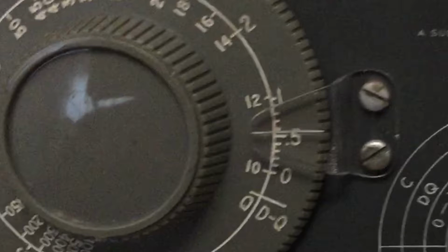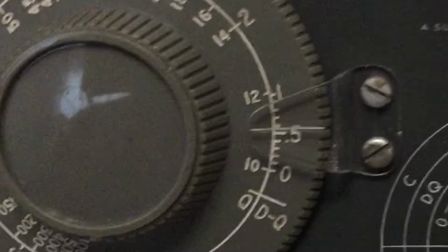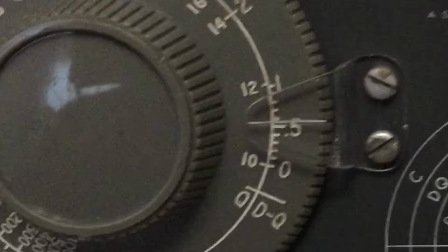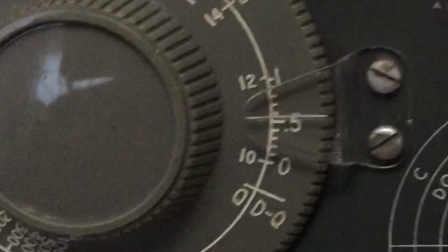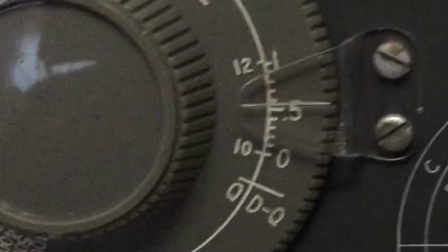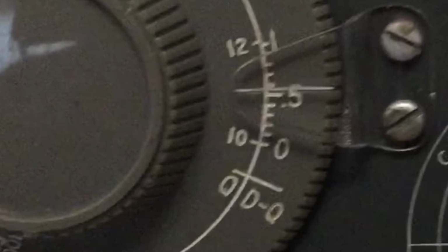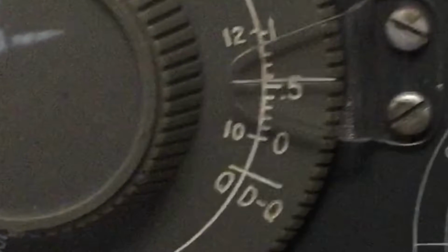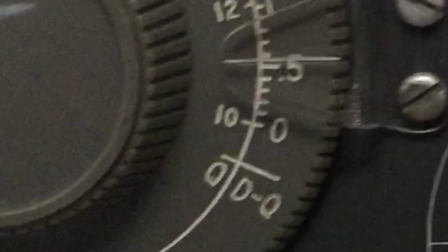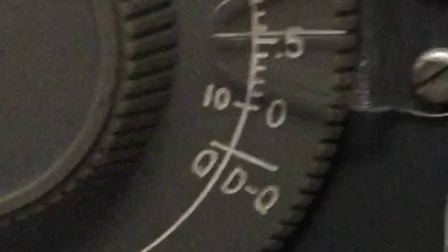Please note that in this video, when I refer to Q, what I'm referring to is Q on the dial. What I actually mean is the dissipation factor, which is 1/10 of the value on the dial. I realize this is quite confusing. The problem is the dial shows Q dq and the function on the side shows C dq. So for the purposes of this, until I start talking about coils and induction, everything I'm talking about is dissipation factor. The reason why I use Q is because it's the Q dial.